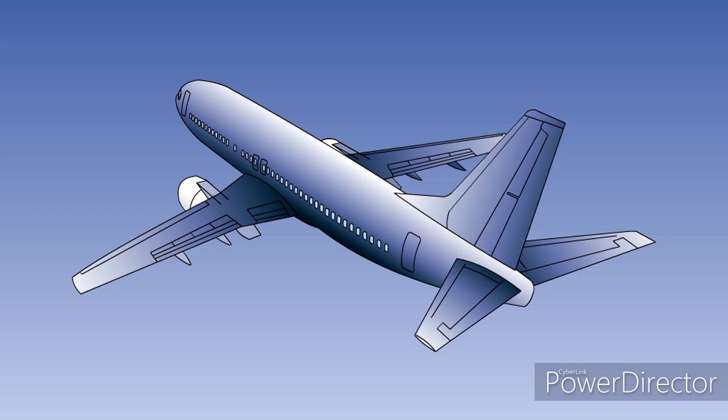Servo tabs tend to be used on larger aircraft, where the weight, due to the physical size of the flight controls, let alone their aerodynamic forces, would produce very large stick forces. The Boeing 737, for instance, normally uses hydraulic power for its flight controls, but has servo tabs as a backup in the event of hydraulic system failure.